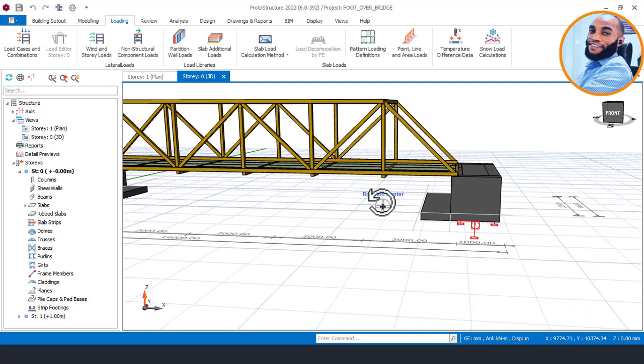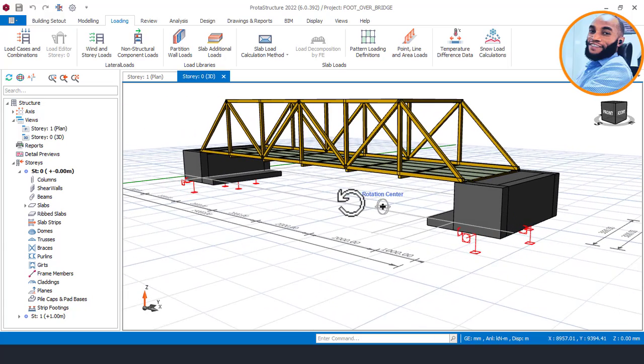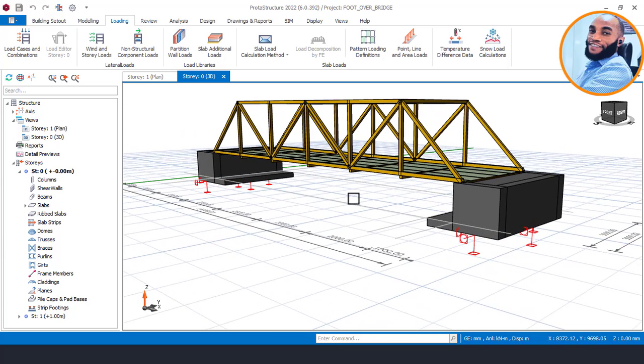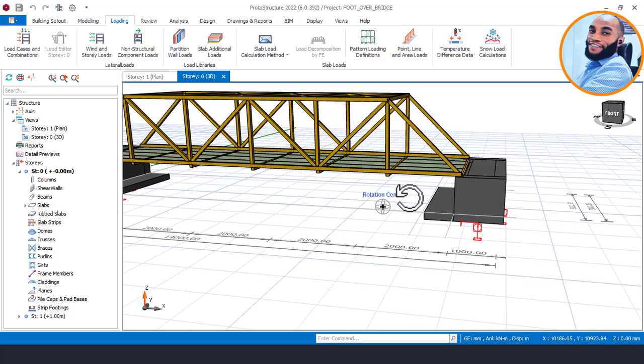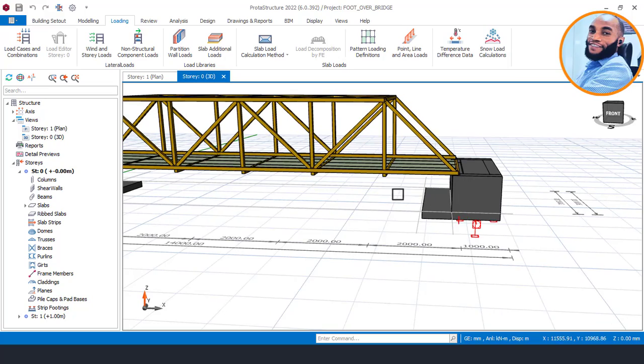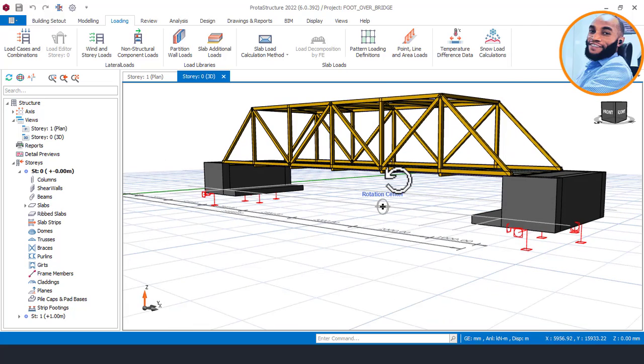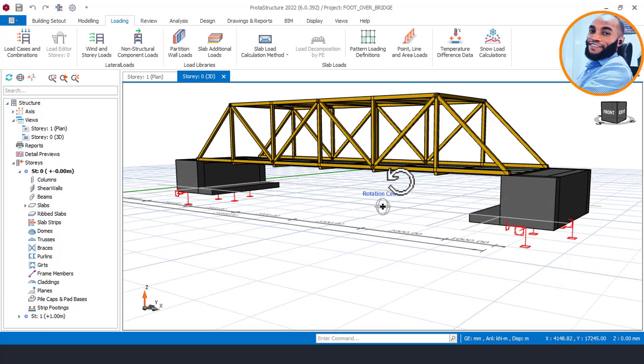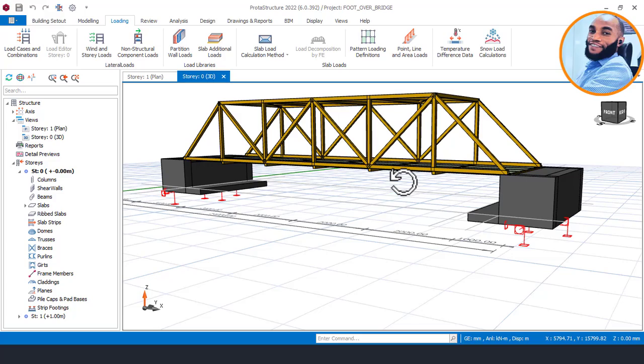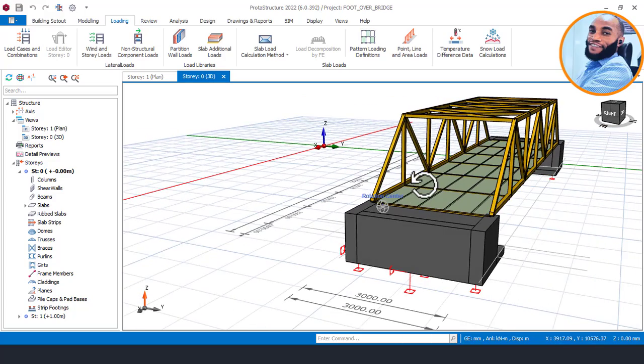Now this particular load comes with Eurocode. It was basically not in the BS code before, but when Eurocode came into existence, they considered possible accidental actions from impact. This load is also applied for buildings. When you are designing a building that is sited near the highway, you must also apply possible accidental actions from impact. So there are various ways where you can apply all this load.